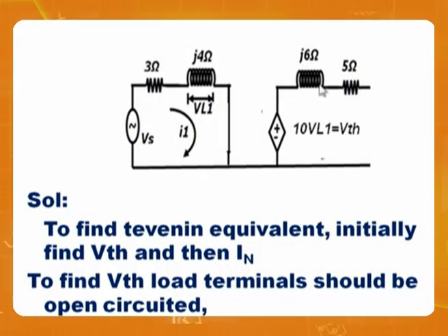Please observe another serious matter. These two are open. When these two are open, the current in this branch is 0. And if the current is 0, the drop is 0. Therefore, the VThevenin is after all just here. Whatever the voltage you get here is the VThevenin. That means whatever the voltage you are getting here, multiply with 10, that will become VThevenin.